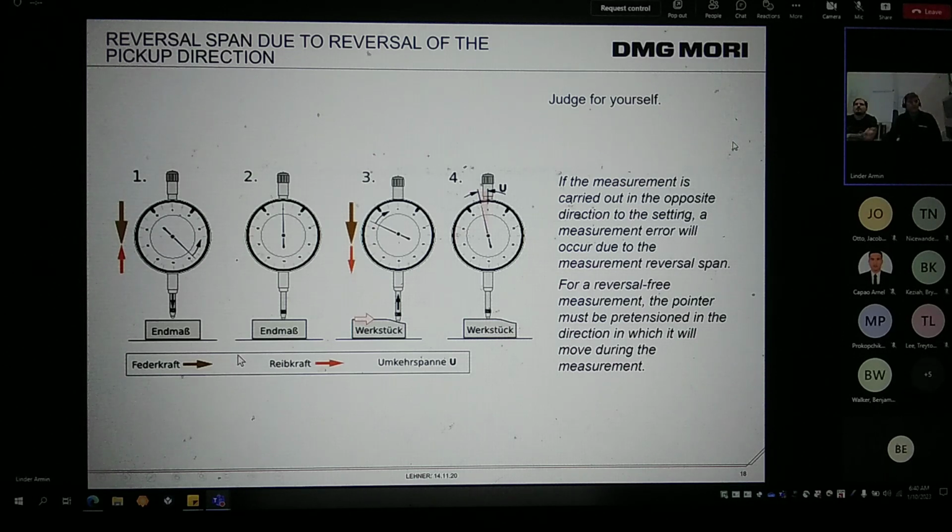If you see, for that example, we have here an end block that we always measure to the point. So there are some forces that we have to consider. You have to be sure that you go with the same speed on it. If you do a counter measurement in the vertical position, you have to be careful to always do it with the same speed, as it also has an influence on your measurement.